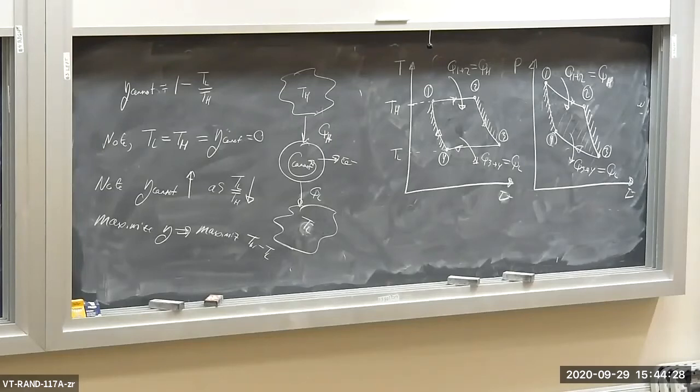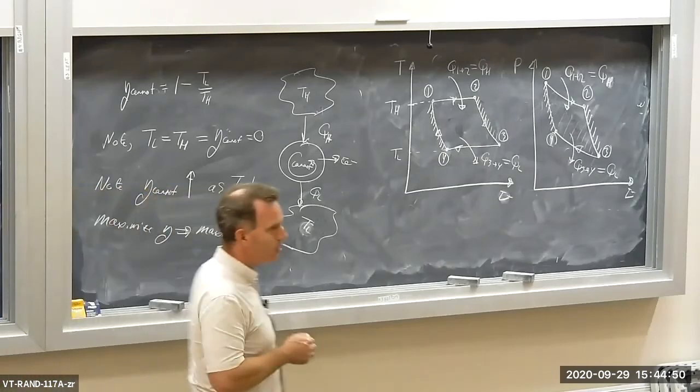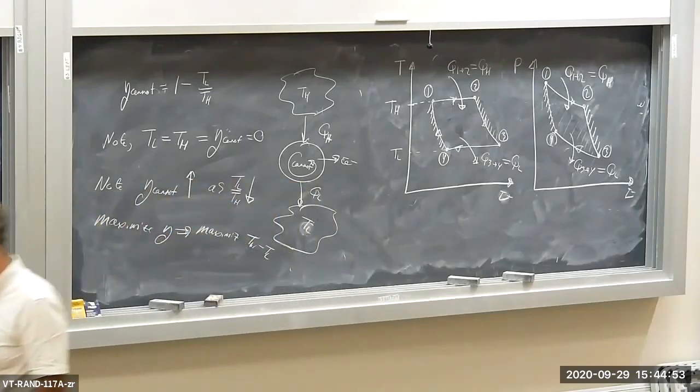This is going to be a constant specific heat problem. I'm going to find a quantity called k, which is the ratio of the specific heat at constant pressure, Cp, divided by the specific heat at constant volume, Cv, and I'm going to set that equal to 1.4. I'm going to assume constant specific heats, and I'm going to fix the ratio of Cp to Cv. This will make it relatively easy to do calculations, as opposed to using air tables, which can be much harder to do, okay? The amount of air, the working fluid, is 0.1 kilograms.